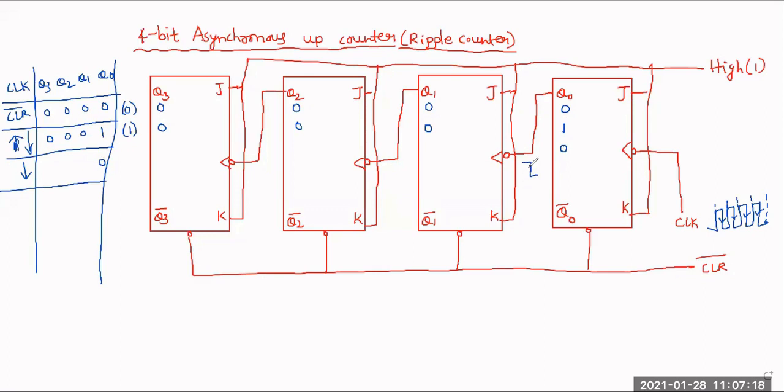నెగిటివ్ ఎడ్జ్. నెగిటివ్ ఎడ్జ్ ఉన్నప్పుడు J value 1, K value 1 అంటే ఇది ఆపరేట్ అవుతుందా కాదా? 1 అవుతుంది. 0 నుంచి 1 అవుతుంది. ఓకే, 0 to 1 అనేది పాజిటివ్ ఎడ్జా నెగిటివ్ ఎడ్జా? పాజిటివ్. పాజిటివ్ కాబట్టి ఇక్కడ ఏమవుతుంది? 0. No change. 0 to 0 అంటే no change. Okay. So when I apply the next clock pulse, 0 0 1 0. So this is 2.